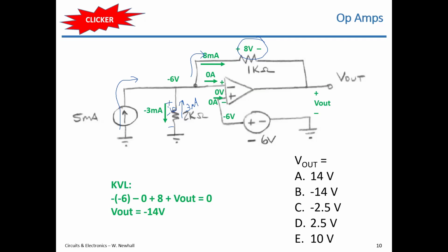Okay. So someone says in the chat, wait, if we can't conclude that it's a non-inverting or an inverting op amp, we can use KVL. Yeah, you can use KVL, KCL, Ohm's law, just like we're doing here. If you can't figure out what an op amp circuit is, what its maybe common name is, and what it does, then you can use the negative feedback approach just like we did here to figure out whatever you're looking for, either the output voltage or some other voltage, or the output divided by input voltage, which is gain. All right.